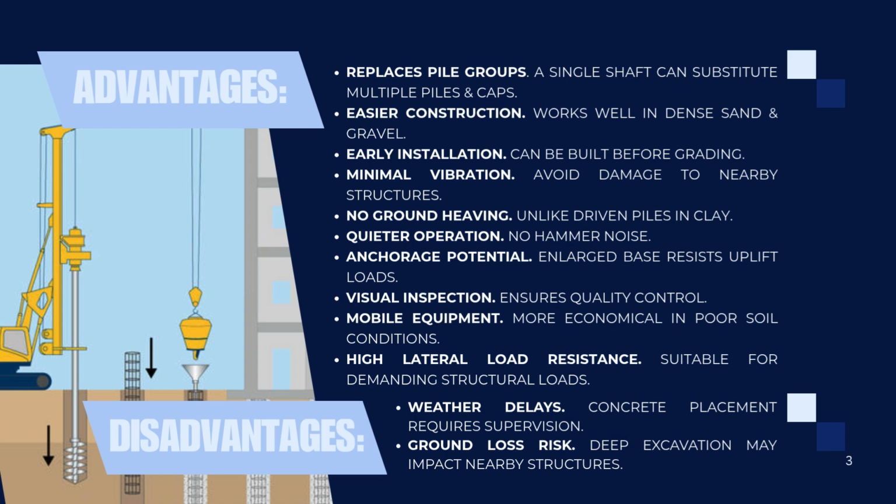They are easier to construct in dense sand and gravel. They produce minimal vibration, making them safe near existing structures. They are quiet since no hammering is required. They provide high resistance to lateral loads. They also allow visual inspection, ensuring quality control. They are also economical, especially in poor soil conditions.